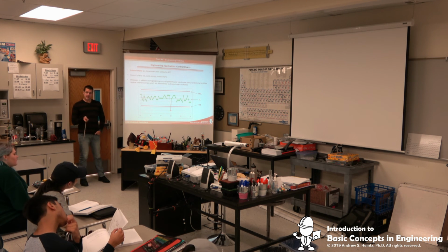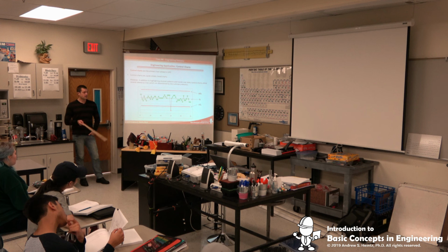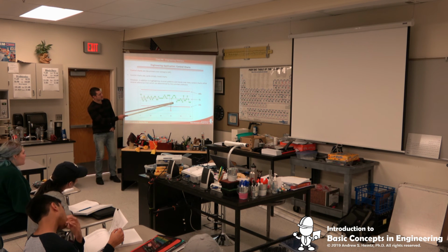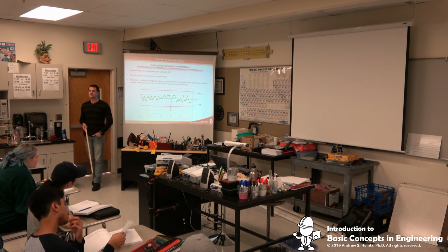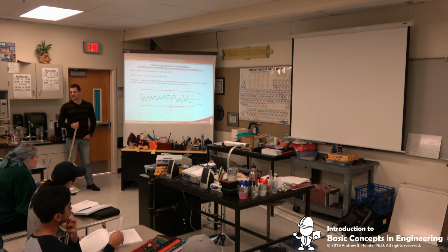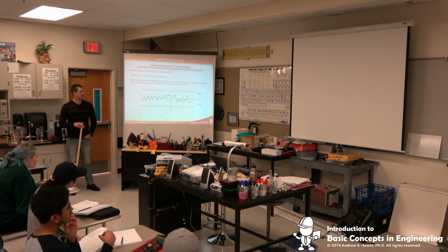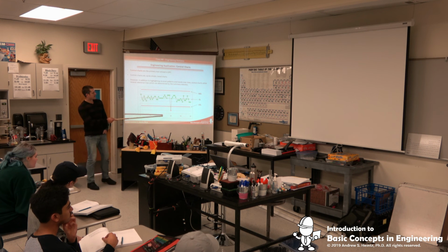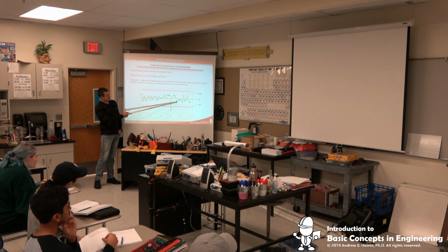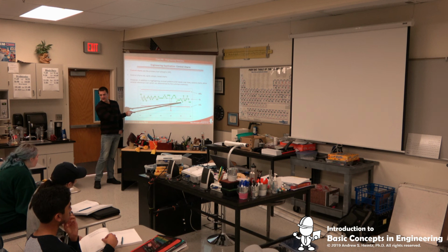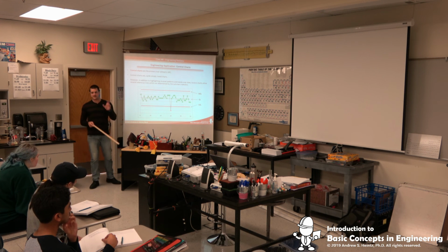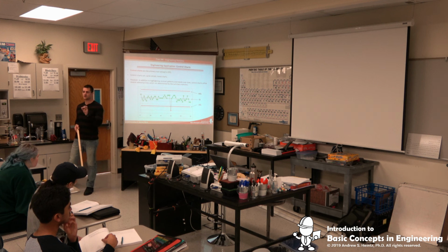So in the example I just had you do in the book, if we were to ever get 8 of these, so there we have 1, 2, 3, 4, oh, but he hit the center line, we're okay. 1, 2, oh, we're okay, right? If we were ever to get 8 of them consistently in a row on one side, we would also flag that point as being out of control. So in that case, let's say there were 8, this point would become red and out of control, and it would flag the engineer to go look at it, even if it was inside the distribution, because that was a rare event.